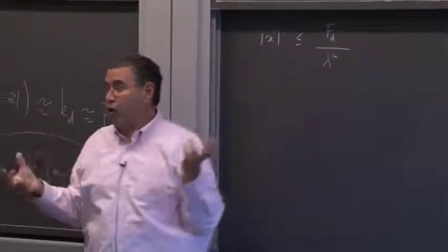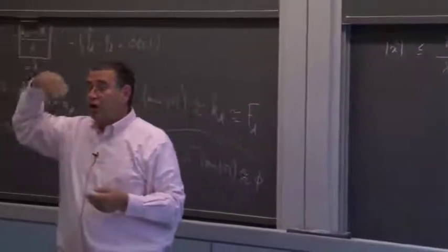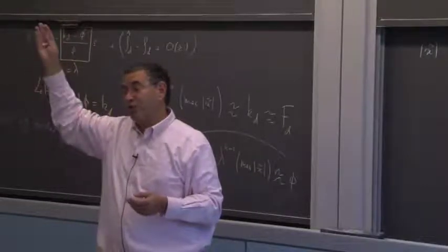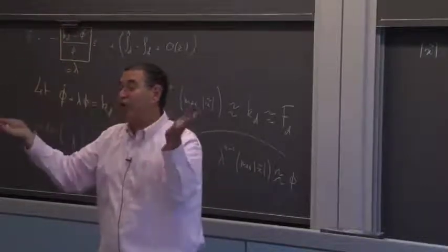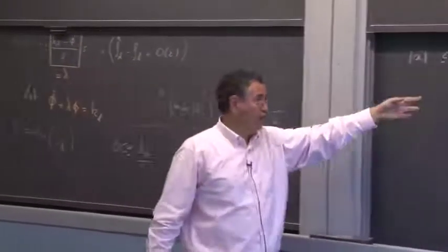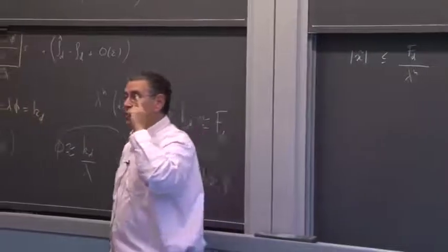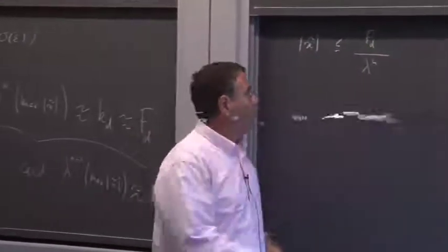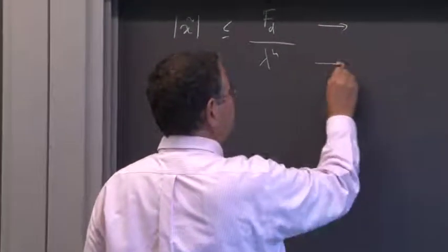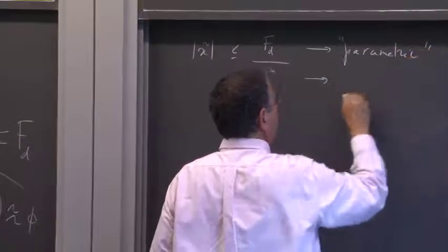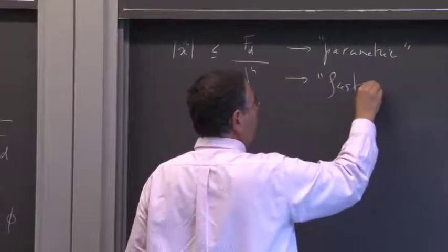The bottom one is uncertainty on unmodeled dynamics, which means in a sense uncertainty on the order of the system. Should we have included this extra vibration term? Which would change both lambda and n. So you have a ratio of uncertainty on so-called parametric uncertainty, and fast unmodeled dynamics.